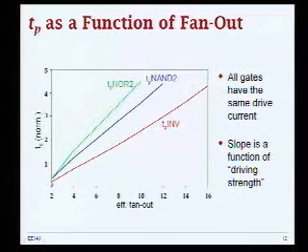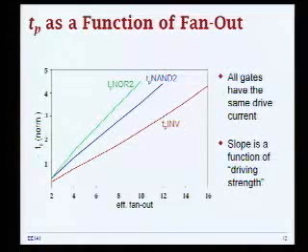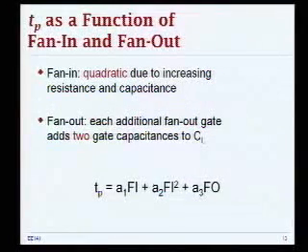So that's basically the same formula. TP is equal to 1 plus fan-out divided by gamma. So what is this value? If you extrapolate this all the way down to 0, then you get your TP naught. And then from here, you have this slope. So this is how this could be modeled, basically. We said fan-in is quadratic, fan-out is approximately linear. This is how you model your propagation delay.